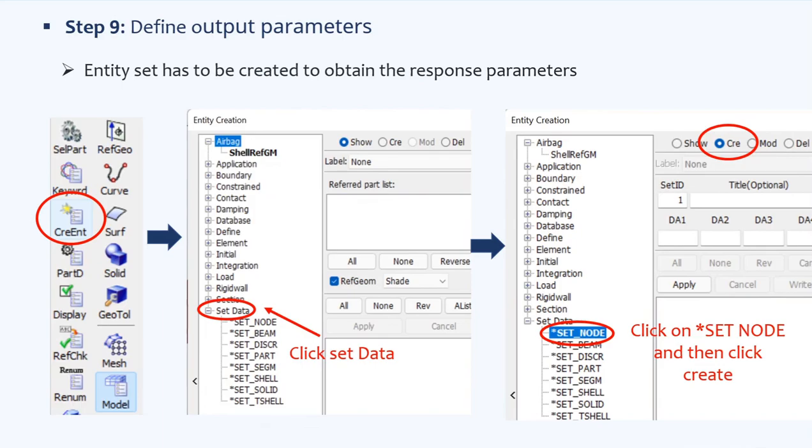these parameters. LS-DYNA won't calculate the values throughout the column, for all the elements or all the nodes. The ASCII output is calculated only for the locations that we tell the software, like at this location I want the nodal displacement history, and at this section I want the element output like stresses and strains. So here we'll discuss how to define the locations for getting these response values.